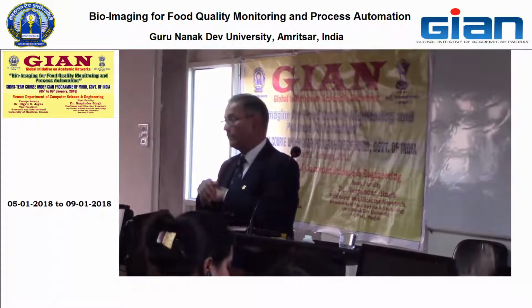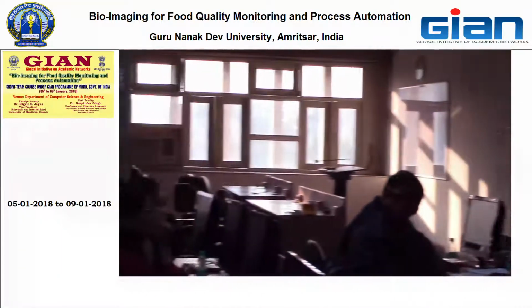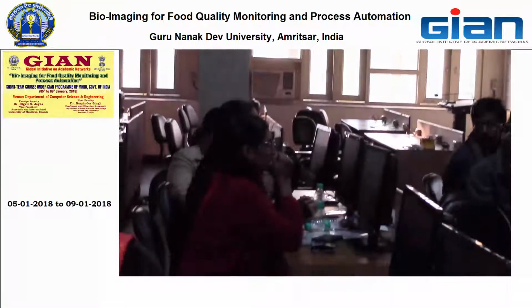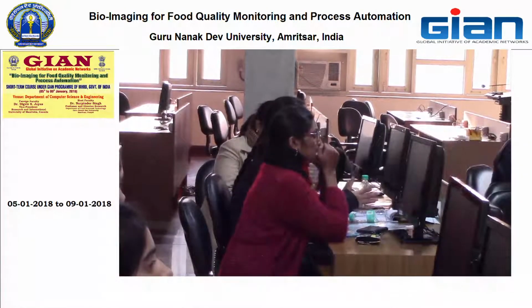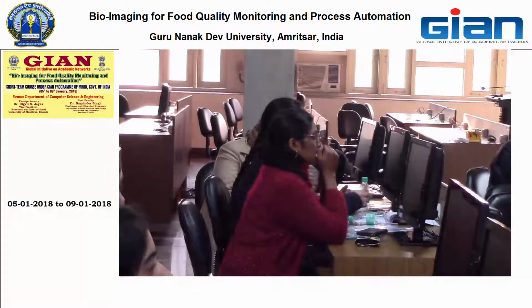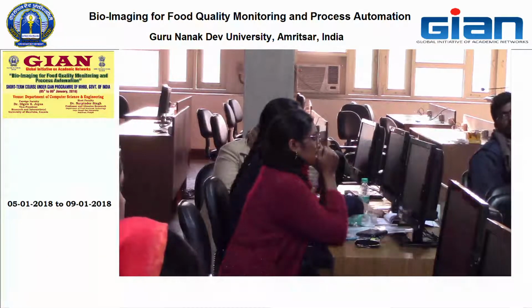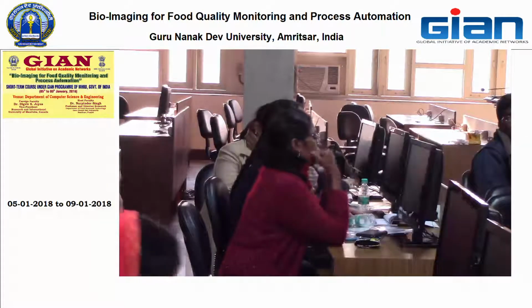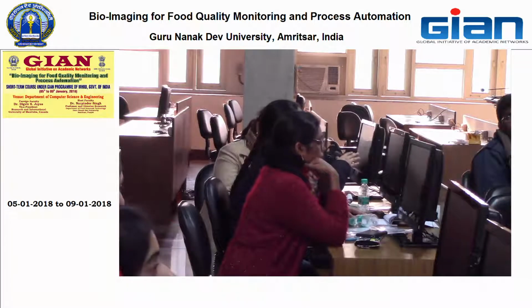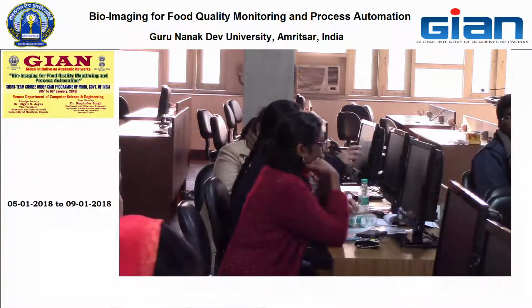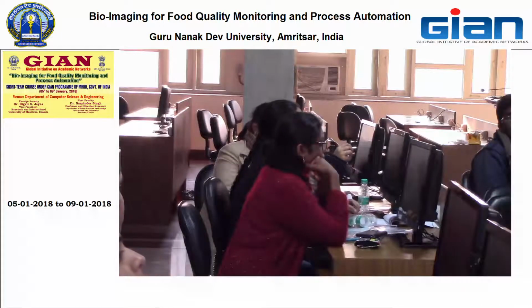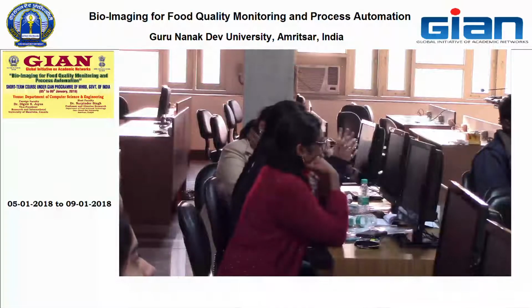Sir, I have worked with NIR in the field, where they use an NIR instrument. First of all, they took known samples with known protein content, fat, moisture, and ash content, and then they fed the samples into the NIR for calibration, let's say 30 samples. And then they put an unknown sample into the NIR and the instrument tells the fat content, moisture, and protein within that calibration range.